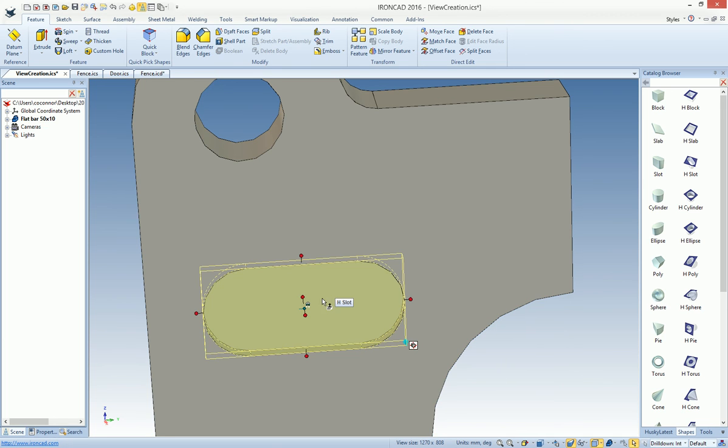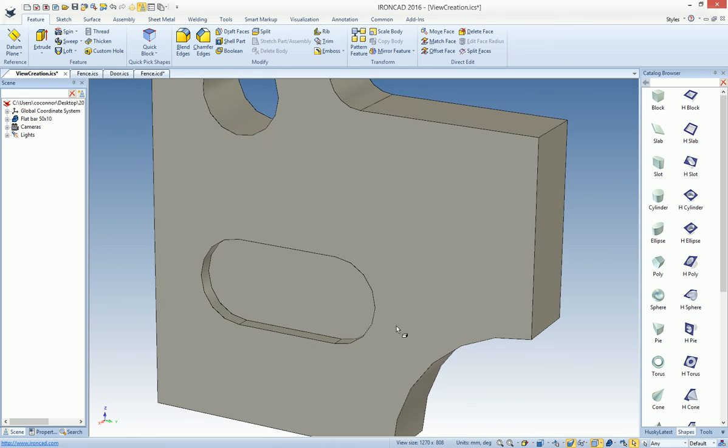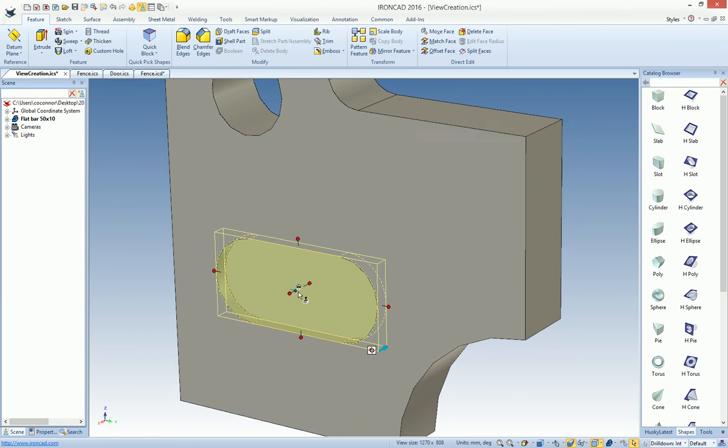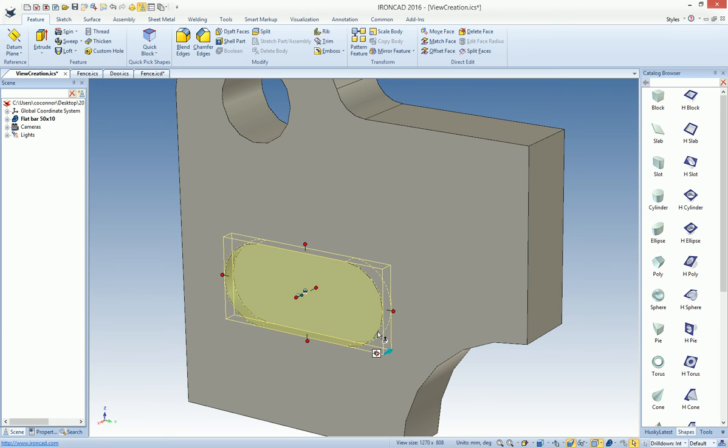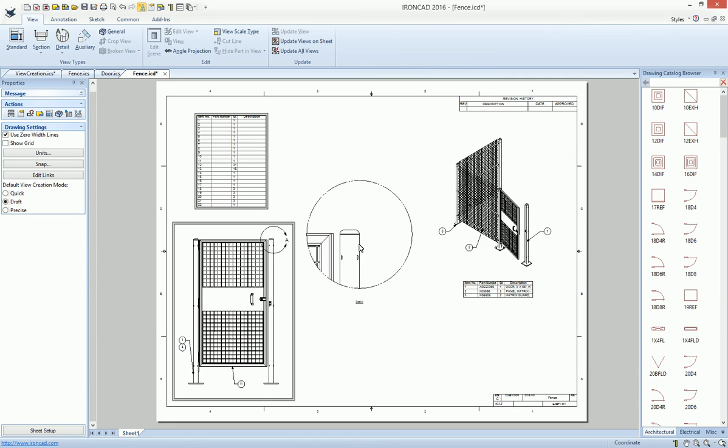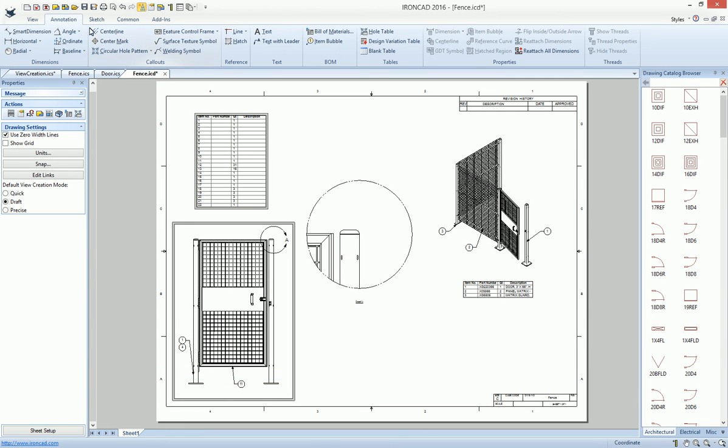What we have enhanced sort of works like sheet metal, if you're familiar with it, the punch centers. We're using the anchor information, so as long as the anchor is in the center, or you can move it to wherever you like, wherever that anchor is for that particular feature, when you go to the drawing, you'll be able to call out a command when you create center marks, or it might be a new command altogether. When you create the center mark, you can actually use the feature information to draw it, which is nice. So now you can get any type of feature that you want, whether it's a slot, a custom profile shape that you need to call out the center for, or a punching location, whatever you want, you can use the anchor to do that, which is really handy on any type of geometry shape.